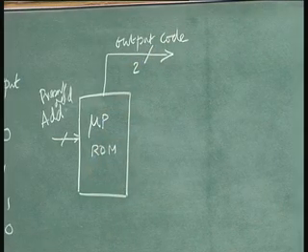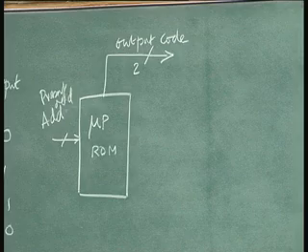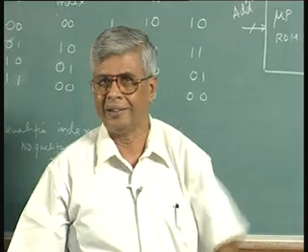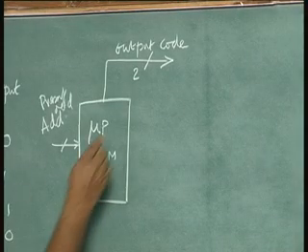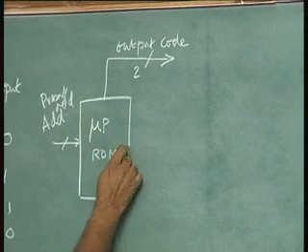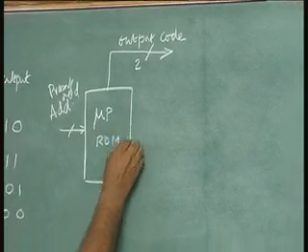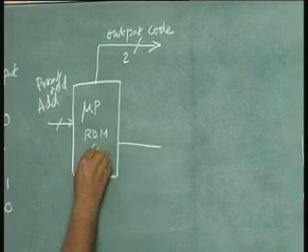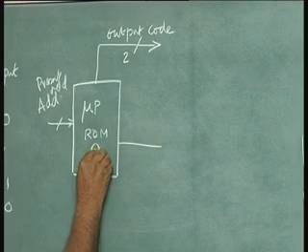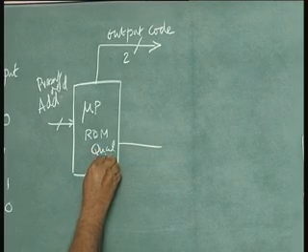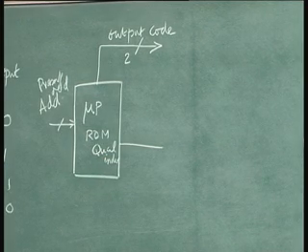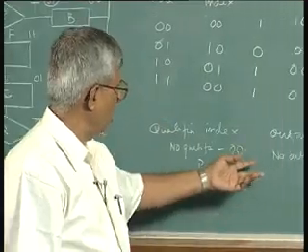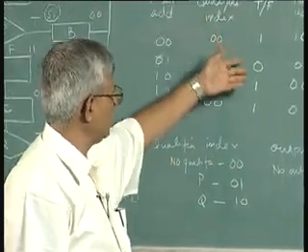Earlier I had a true address coming and false address coming, one of them was selected using a multiplexer. Now I do not have to do that, I will have only the qualifier index, which is n plus 1, if n is the number of inputs, actually it is logarithmic value of the total number of inputs.